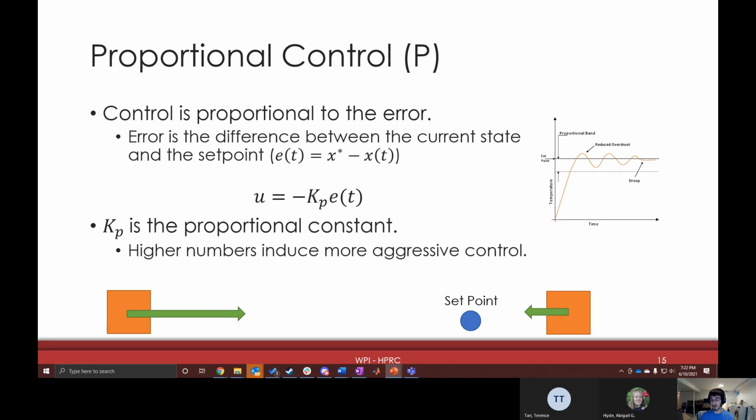On the right, we can see what the input response of a PID controller would look like. In this example, we have our set point and we start from a temperature of 0, and you see it goes up and then it overshoots a little, and over time it damps down. The oscillations get smaller over time. Theoretically, in a mathematical sense, you'll always have some oscillation. But in a practical sense, the oscillation eventually gets small enough that you can't perceive it.